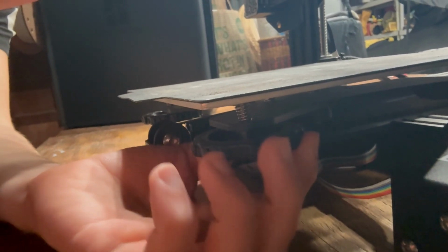It's got these little screws underneath and you have to twist them up slowly and put a piece of paper between the bed and the nozzle. You gotta figure out that distance. It takes a while and it's pretty tricky. The BambuLab does it automatically, which is great. Every single 3D print, the first layer is perfect. So that's pretty awesome.